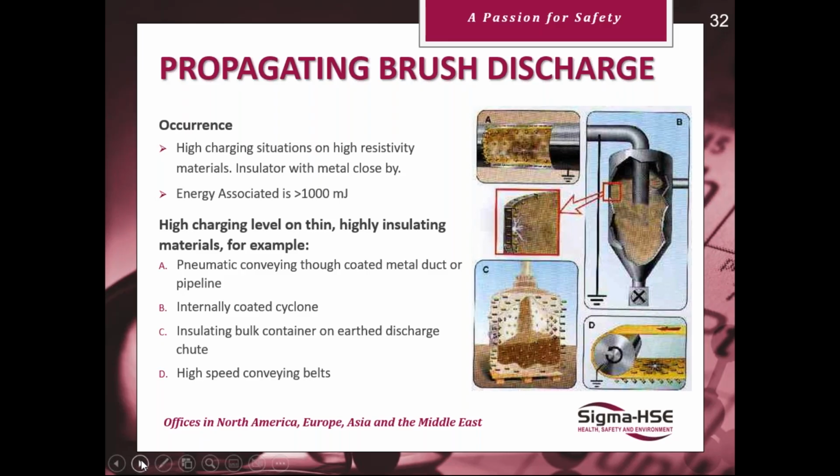So he went to push it down, and we had acetate sheets stuck to the side of the steel bulk container, and he got a propagating brush discharge. The whole of his arm went jet black and blue, and he was in hospital for 6 days and had basically a heart attack on the machine caused by it.